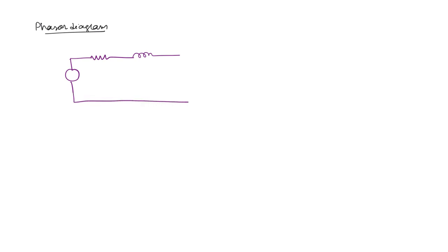Okay, we will now try to draw the phasor diagram for various kinds of loads, right. So this was the equivalent circuit that we have derived, right. This is the generated voltage, we will take it as E, or you can write Eg. This is the armature resistance and the synchronous reactance, and the armature current you can take as IA. Now here you are going to connect a load. Now this load can have a unity power factor, lagging power factor or a leading power factor.